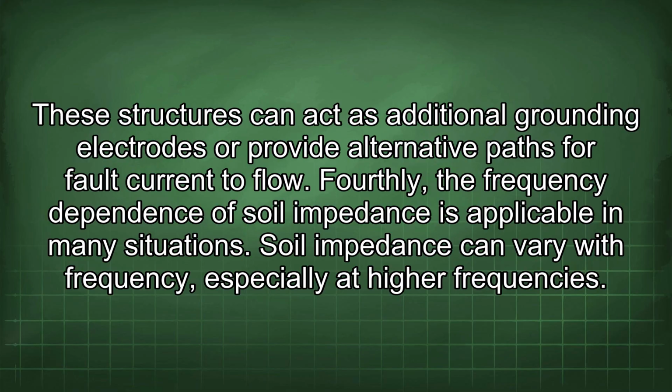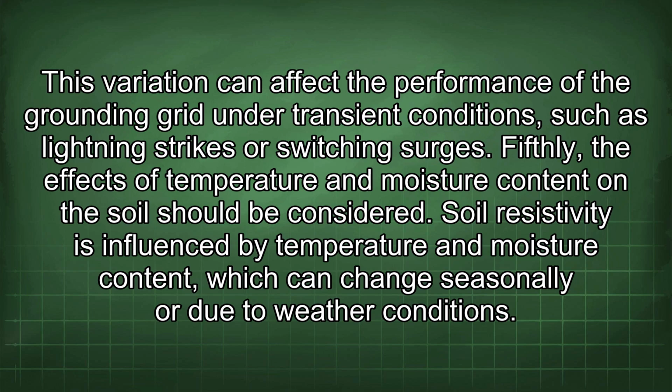Fourthly, the frequency dependence of soil impedance is applicable in many situations. Soil impedance can vary with frequency, especially at higher frequencies. This variation can affect the performance of the grounding grid under transient conditions, such as lightning strikes or switching surges.